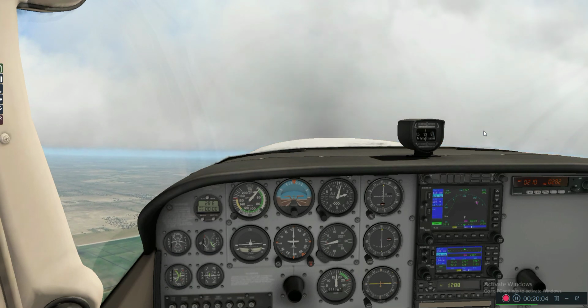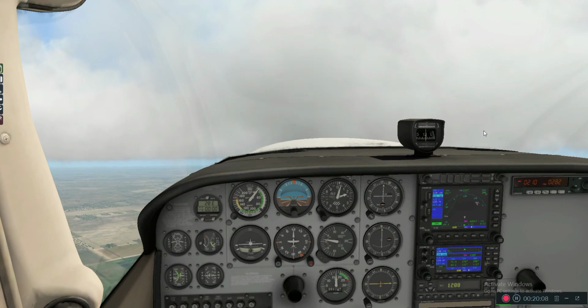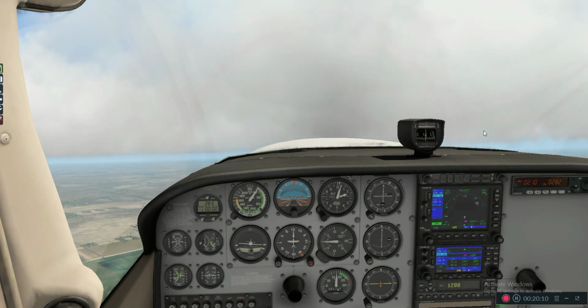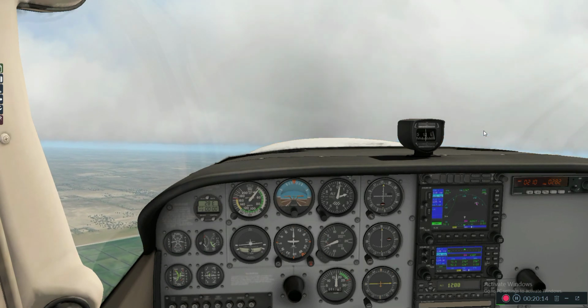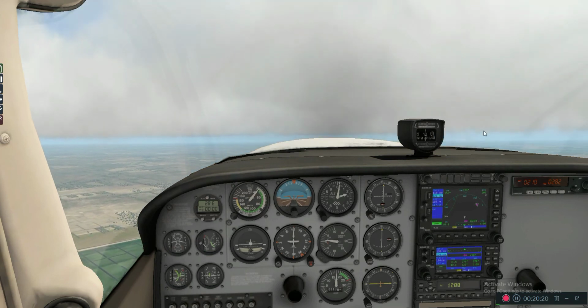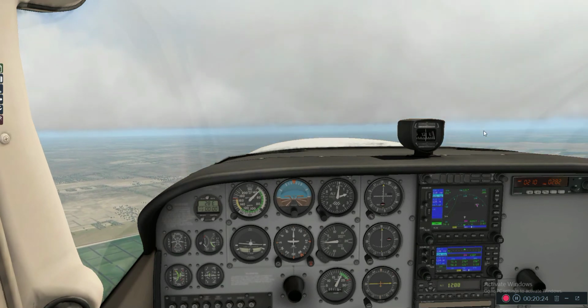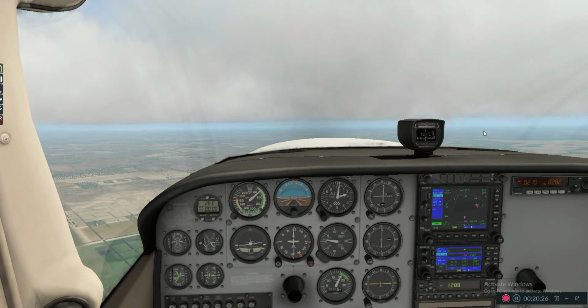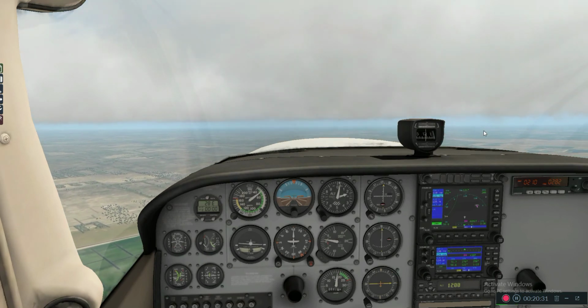So right now I'm doing it with the stall horn on. This is sort of the old way, right? Trying to maintain altitude, manage power, and keep that stall horn on. A little bit of up and down pitch there, and that's just me correcting and sometimes overcorrecting. But real slow flight would be more like this. Add some power. Get into that green arc a little bit. There we go. There's 55 knots.